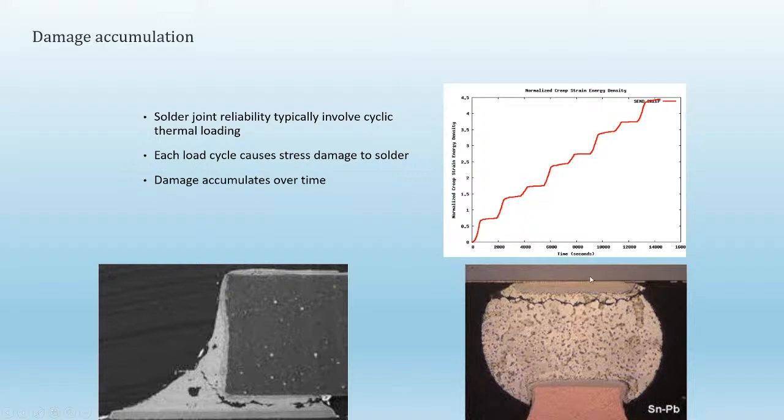Each load would cause the stress to damage the solder more. So it may take a certain number of cycles for a crack to initiate, and after that, each cycle would tend to cause a crack to grow, and eventually the solder becomes unreliable. There's less contact between the two materials, so signals may have issues.